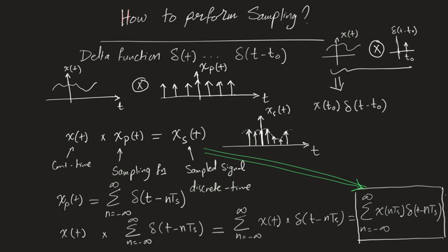So they have sampled that function. Okay, excellent. The question comes, how to pick Ts? And that is the part where we ask the question, what are the conditions to perform proper sampling? So how to pick the value of Ts, the value of the sampling time? I can actually make those guys close to each other or far from each other, right?